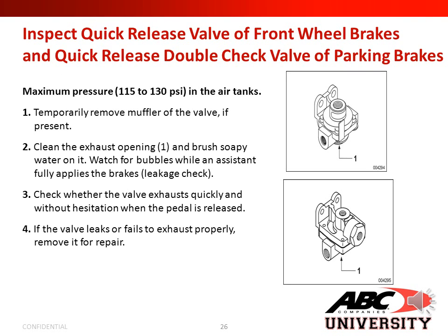Next, we'll go over inspecting the quick release valve of the front wheel brakes and the quick release double check valve for the park brakes. The pictures to the right, on top is the quick release valve of the front wheel brakes, and the picture below is the quick release double check valve of the park brake. Before you begin, ensure you have maximum pressure, 115 to 130 psi in the air tanks.